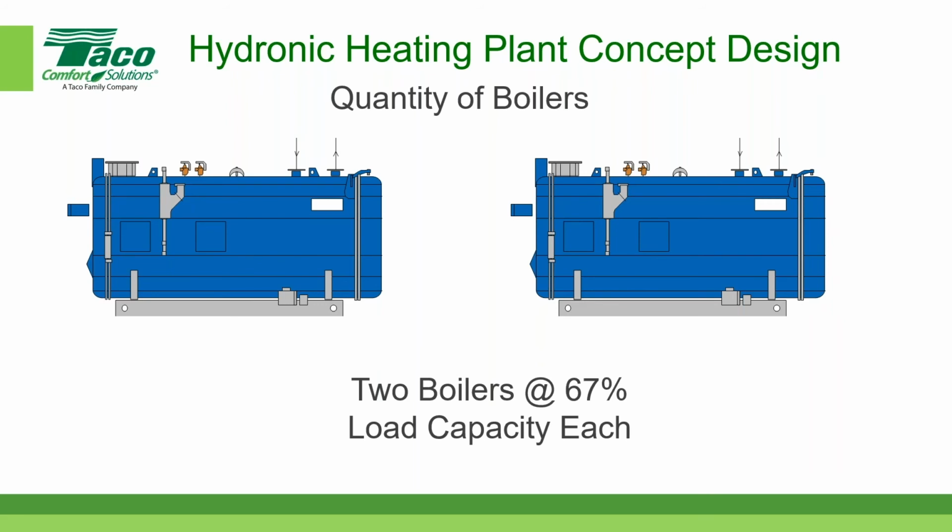And Bryce made a comment about another negative for one boiler is a potential for significant issues with cycling or inadequate water side flow to keep the boiler running. Good point. Yes, that's an excellent point. I'm glad someone brought that up. So yes, if you have a single boiler, you could potentially have a short cycling issue. So that's an excellent point.